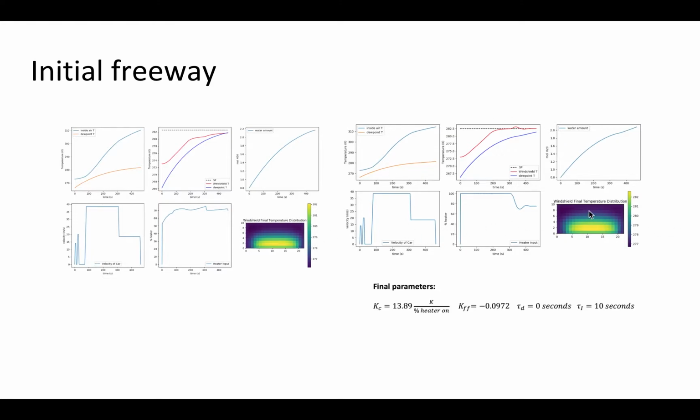As you can see, the tuned controller performs much better than the initial controller. The initial controller doesn't even reach the set point over the entire time horizon, whereas in the tuned case, it reaches the set point and maintains it. The increase there is from the drop in the disturbance variable, but the controller is able to handle that very nicely as it stabilizes at the end.